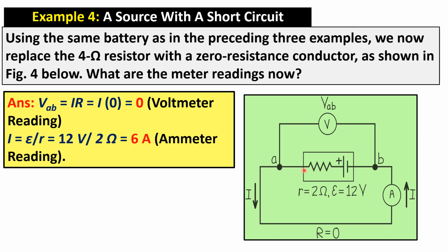Okay, we can also put it this way. Even if there's a wire connecting point A and point B, that happens to be of high resistance, so the charges would rather move through a path with the least resistance, and that is this path instead of moving through the voltmeter.